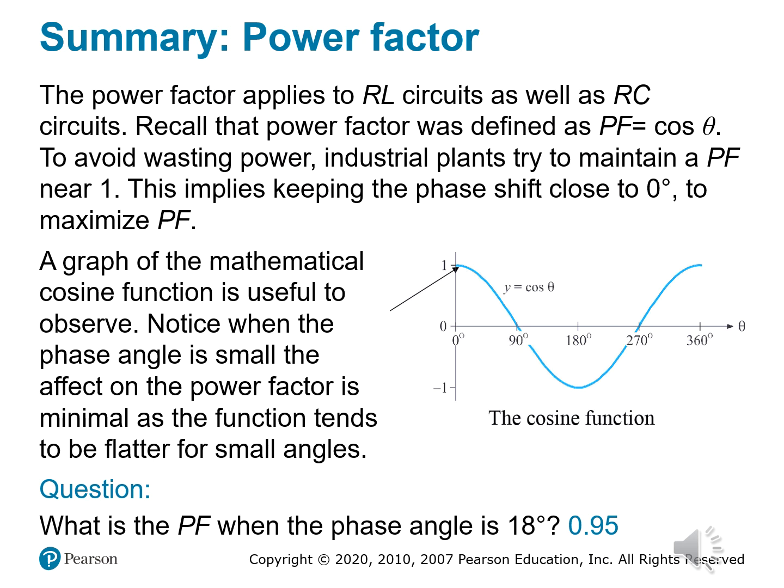The final tip is how to improve your power factor: you might have to add capacitors in purely inductive systems. You can use power factor correction in circuits, and designing with proper load balancing also helps improve power factor.